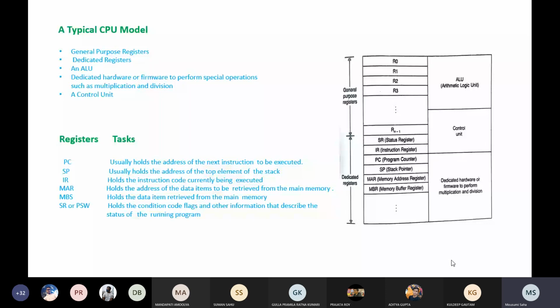All these components you have already seen when I explained the 8085 architecture. Registers, normally we have two types here: general purpose registers and dedicated registers. General purpose registers, the accumulator is one example, and dedicated registers, you can say the program counter and the stack pointer. They always store the memory address. Some registers we can use for storing the address and data, those are basically the general purpose registers. But in your dedicated register you cannot store the data, it will always store the address.